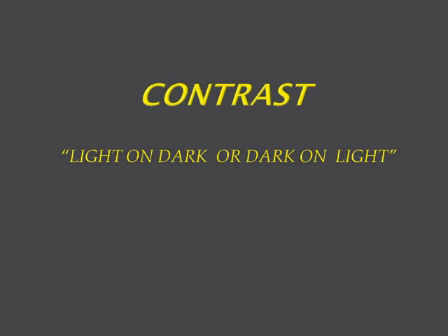Contrast, what color should these things be? The national spec, ADAAG, used to have 70% reflectance. They've taken that out, gone away from there, because when you put a light meter on these things, it depends on what time of day you're measuring the reflectance, and it also knocked out a lot of colors and a lot of products that were actually fine. So they went with a spec that said light on dark or dark on light. And that's probably one of the vaguest specs I've ever seen. So the best thing I can do really is to tell you why we need the contrast, what it's for.